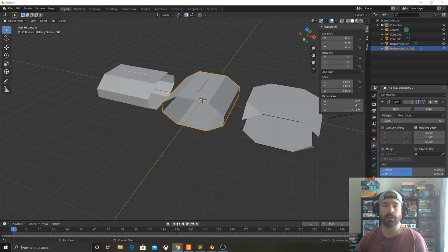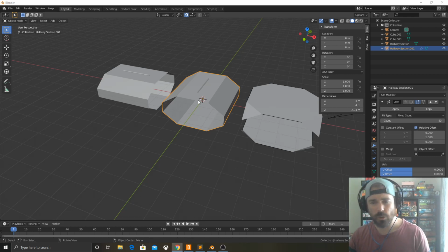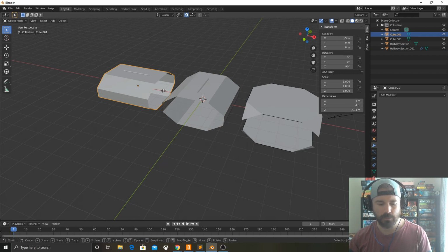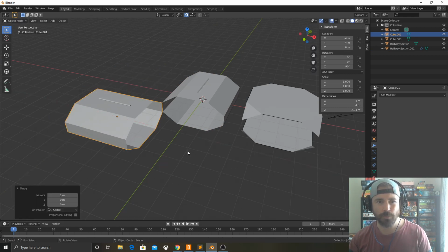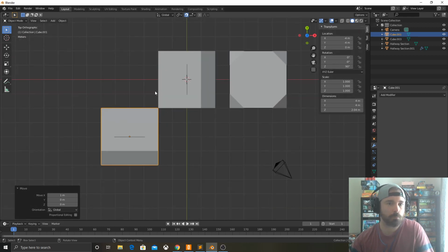And some of you are doing like the science fiction kind of modular dungeon system that you'll have to import into Unity or whatever. And this is kind of what I want to talk about. So what I saw some of you struggling with is trying to get things to line up. So for example, trying to get these things to line up on the corners. And the best way to do it is to actually use the grid in Blender to build everything modularly, because that's the idea behind it. Don't just guess, actually build things modularly.